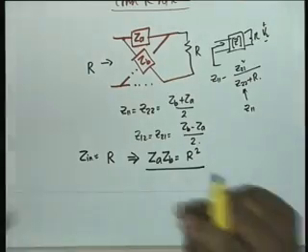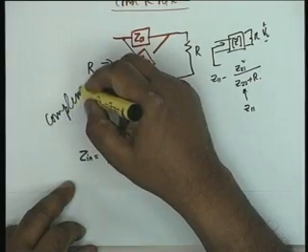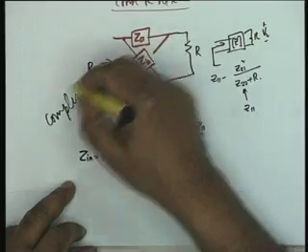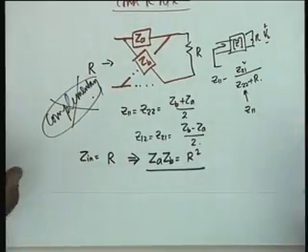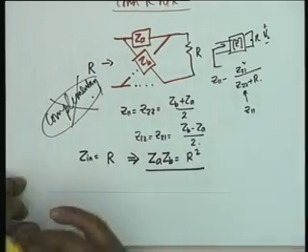In other words, such networks, such impedances, well, let me introduce a term, such impedances which when multiplied with each other give a constant are called, no, I would not use that term. It's not a very appropriate term. I was hesitating. They are called complementary. So forget about it. The question is that ZA ZB equal to R squared. This is the condition.